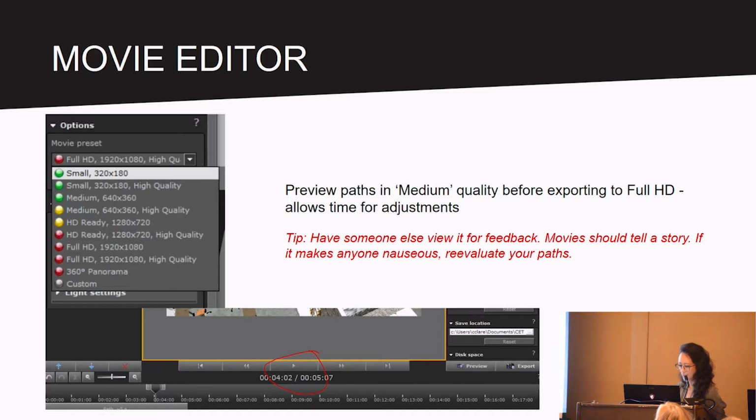So, when it comes to previewing your path, your entire video, I like to render it in a medium quality before exporting to full HD. That way it allows time for adjustments. This is when I'm constantly reviewing it over and over again, and I don't want to spend a whole day letting it render and then realizing, oh, I have to add a plant, I have to add a chair there, oh, why is my furniture floating? I have to fix all that.